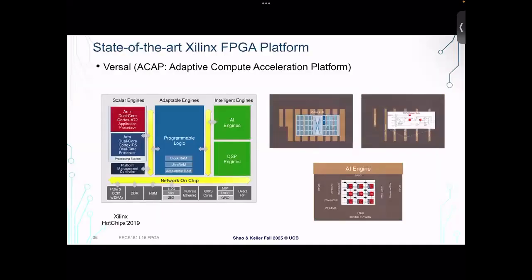Okay, yeah, and so they call Versal this ACAP. They're trying to move away from the FPGA branding, and they call it a whole new thing, which is Adaptive Compute Acceleration Platform, where again, there is still some programmable logic, right? It still is fundamentally an FPGA, but there are all these cool little widgets. Here are the ARM cores. Here are the AI engines. Here's the DDR memory interface, PCIe, HBM, Ethernet. They've added tons of bells and whistles to try and make it as useful for as many specific use cases as they can.